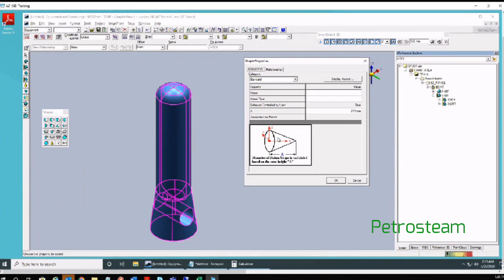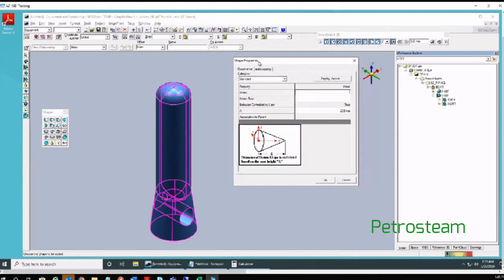It is like a cone like this. By default, some value for this length will be available. You can accept as it is, and do not give any name. For a datum point, it will automatically take some name by itself, like DP1, DP2, and so on. You accept as it is without a name. You have selected the parent, and then you have selected the datum shape.